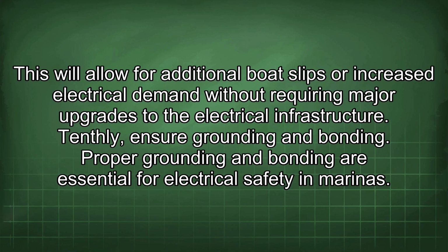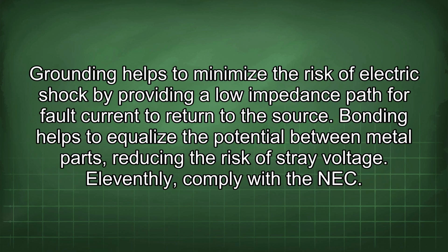Tenthly, ensure grounding and bonding. Proper grounding and bonding are essential for electrical safety in marinas. Grounding helps to minimize the risk of electric shock by providing a low impedance path for fault current to return to the source. Bonding helps to equalize the potential between metal parts, reducing the risk of stray voltage.